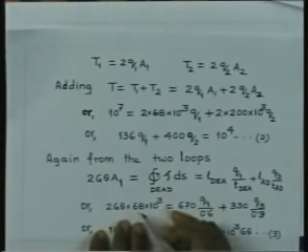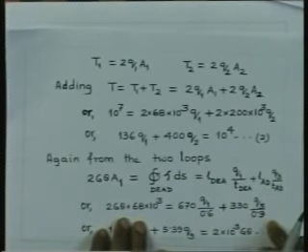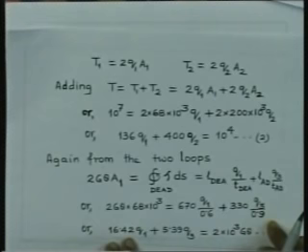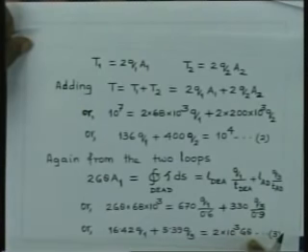Now, we can substitute the values of the areas and also the thicknesses, and then we get this relationship. On simplification, this turns out to be 16.42 Q1 plus 5.39 Q3 is equal to 2 into 10 to the power 3 G theta, that is equation number 3. So, we get another relationship involving the two flows and the angle of twist per unit length, theta.